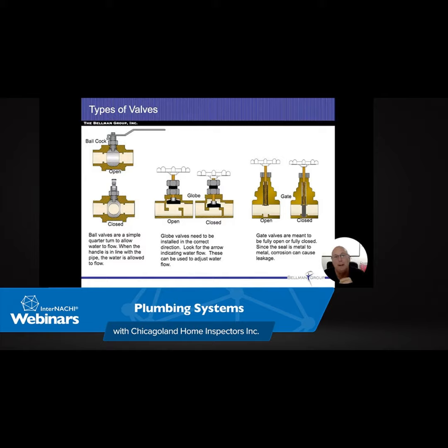I found that if we're within 5 feet of a soil stack, and most of our soil stacks are going to be right wherever the toilet is, they kind of keep them close to where the bathrooms are. So if my sink and tub are within that range, I don't have to run a secondary vent or branch vent to it. You may. There's nothing wrong with it.